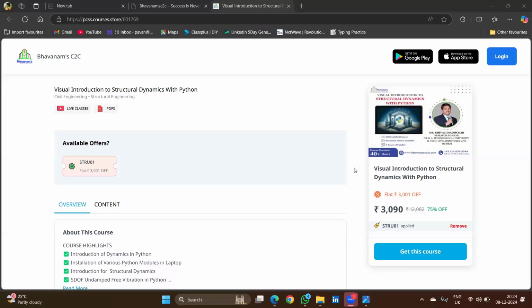This is quite different because you have to give nonlinear parameters. ETABS also has a certain degree of nonlinearity which you can introduce, but in Perform 3D you can do completely fiber-based nonlinear modeling. In ETABS we use 1D elastic elements and 2D elastic elements.